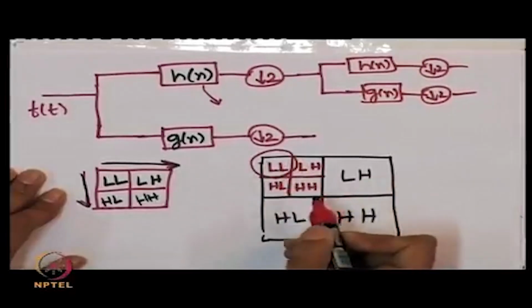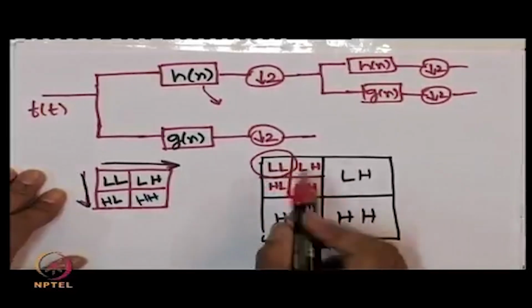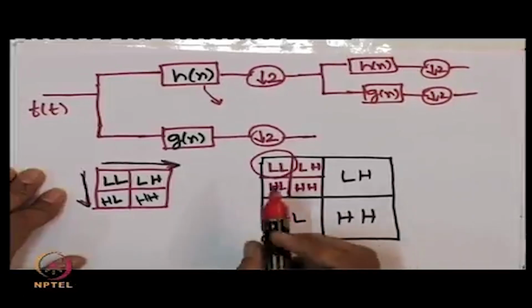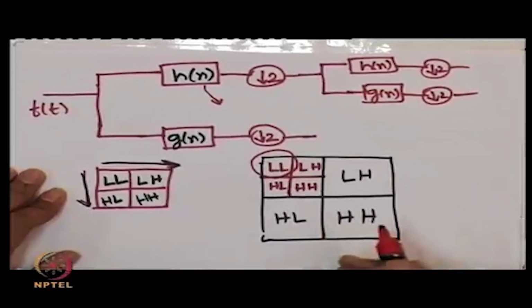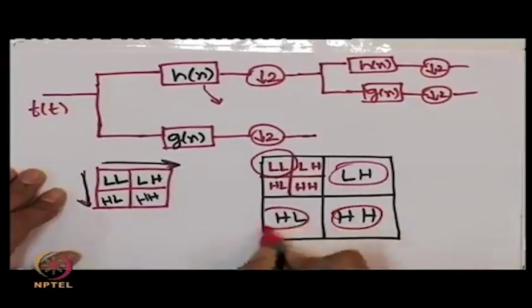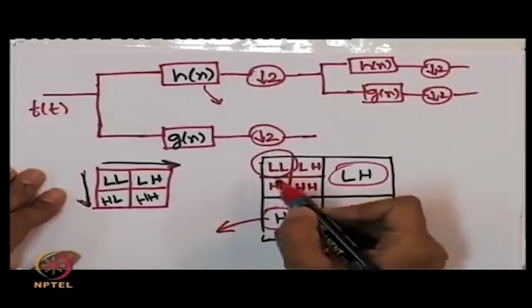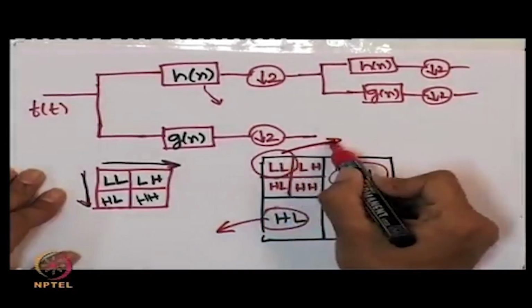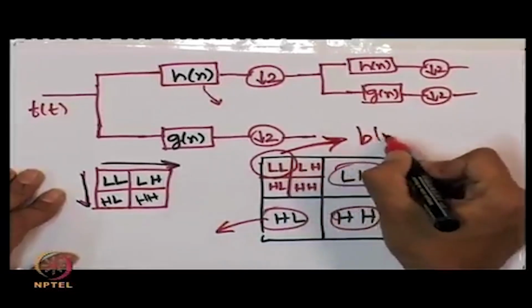It will be sufficient for a low resolution phone to display this image using fewer bits. But if you have a high resolution phone, then we send the whole image, and to reconstruct the high resolution image, you can add these detail components into the image. If you want to see a low resolution version, you can see this LL band. It will look like an image, but the details are missing. It's somewhat a blurred version of the image.